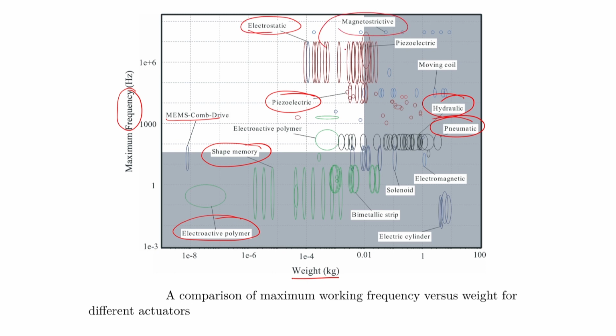So, that is another point. While choosing the actuators, these are the two concerns that you will always find: what is the force versus what is the weight of the system, and what is the stroke level. So, force and the stroke.